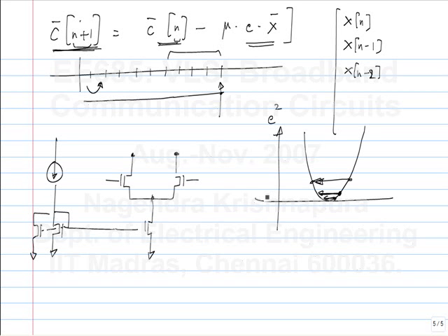With the full LMS, the value of E itself gives you the step size. It is the value of mu times E. So as the error gets smaller, the step itself gets smaller. Whereas with the sign LMS, the step is always mu. So if the value of mu is very large, the final steady state error will also be large. So you want to reduce the value of mu.